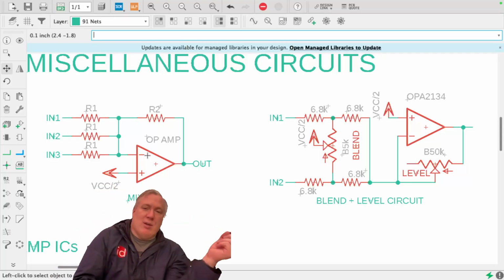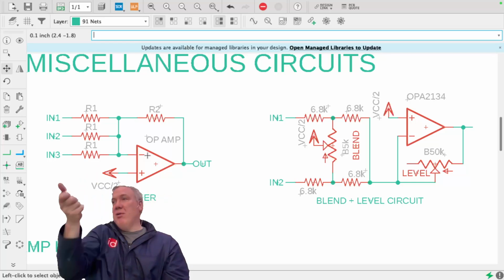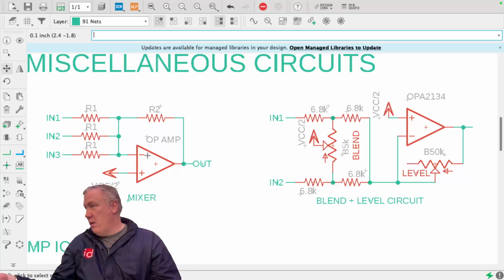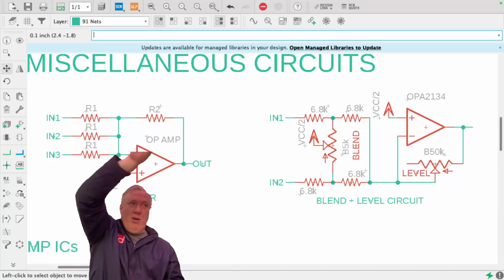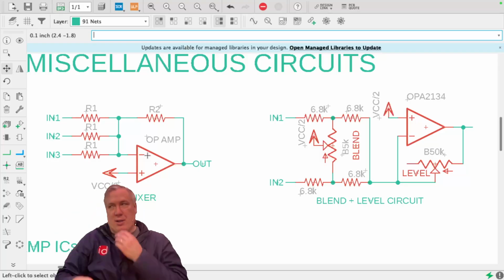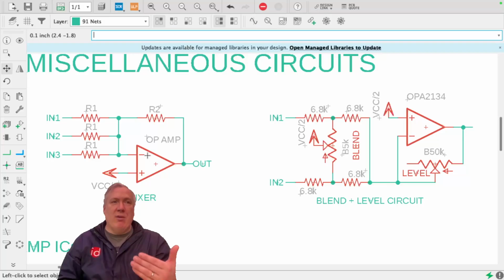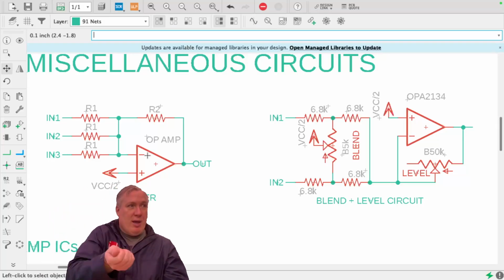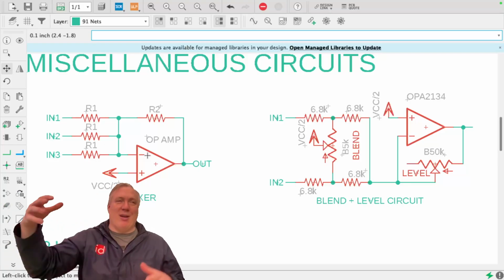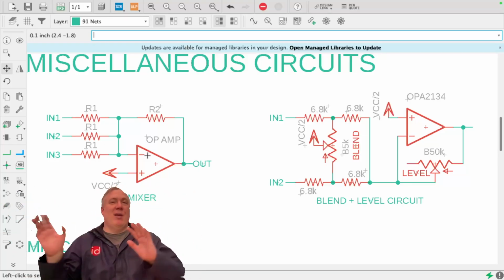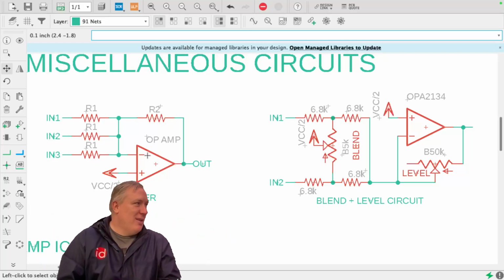This blend circuit is when you want a single knob to go from one thing and blend it all the way over to another thing. Okay? An example of where you would definitely want this is the compressor. You definitely want to go from no compression at all up to only compression. There are other times where there might be a reason for it. So if you had an echo, you could go from no echo to only echo, but that would only be if you were using it in a specific scenario like an effects loop and an amp. Unless you know you need only echo, then I would just not use the blend version.